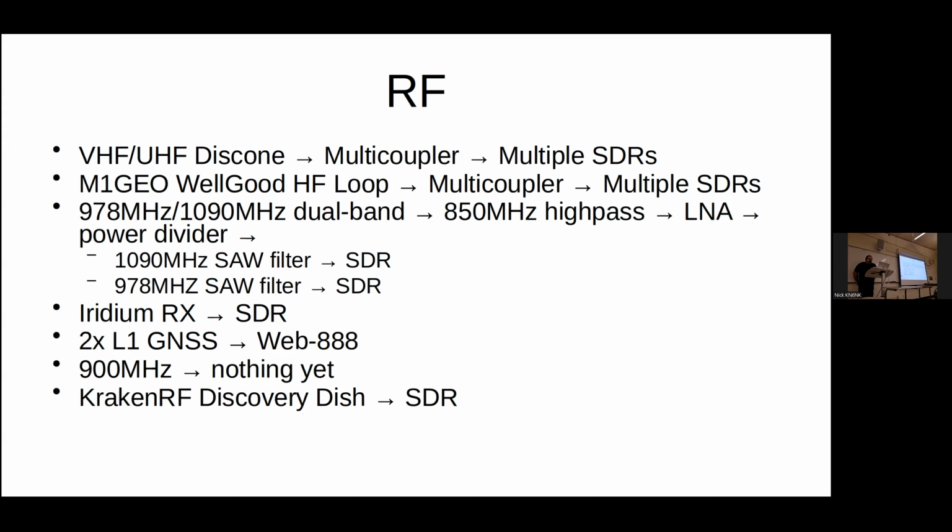Mark Smith N6NK has had to develop an AM band stop filter, just so that he can actually test his own stuff down there. But yes, I have had problems with H-70, the CHP aircraft, or helicopter. When it gets close enough, it will overwhelm the LNA that I have in front of the ADS-B receiver, and so it will basically drop out. It just overloads it entirely. That's on the helicopter ADS-B translator?